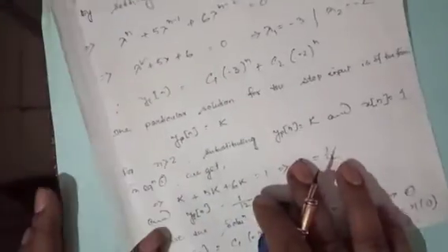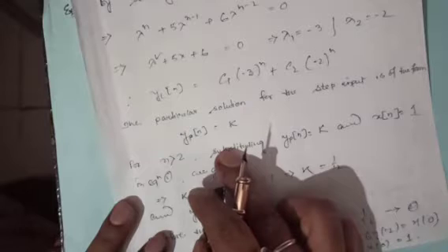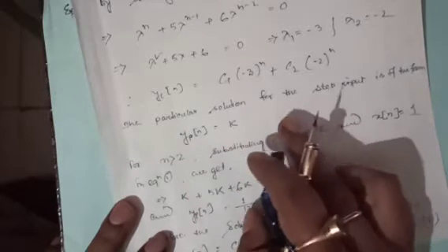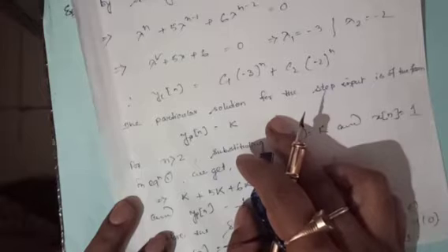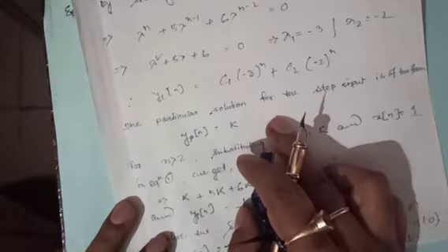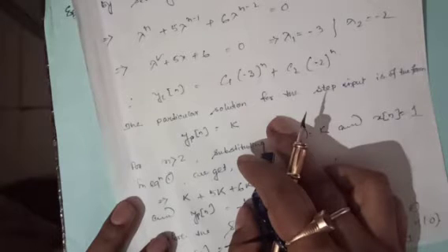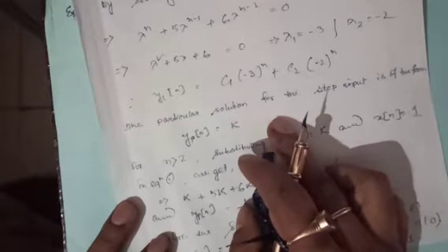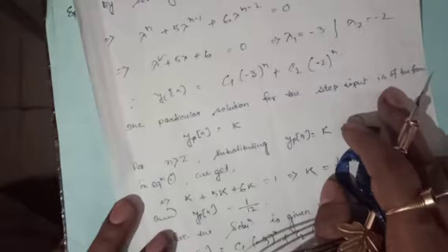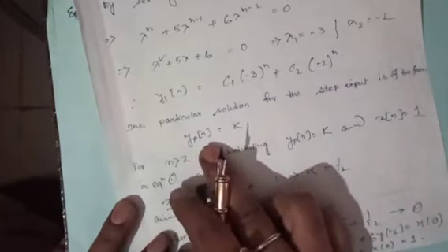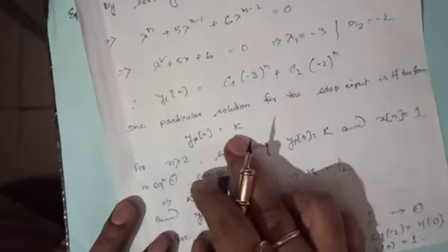Okay, so as you know, the step is denoted not exactly as unit step, so step is nothing but k into u of n, where k is any value. Unit step means the value is 1. So when it is a step, the value can be other than 1 as well. So let me put it as k. So the particular solution for the step input, that means there is no initial condition, the system is initially relaxed. Therefore yp of n, that is the particular solution, is equal to k.